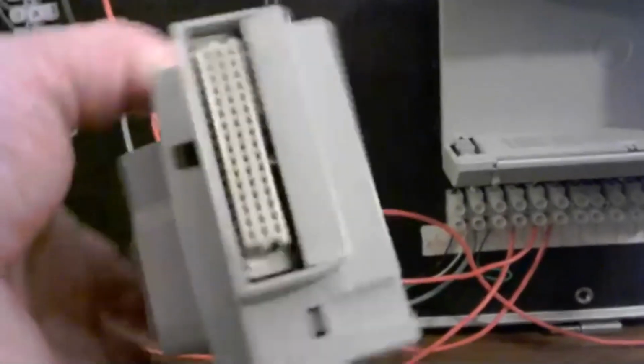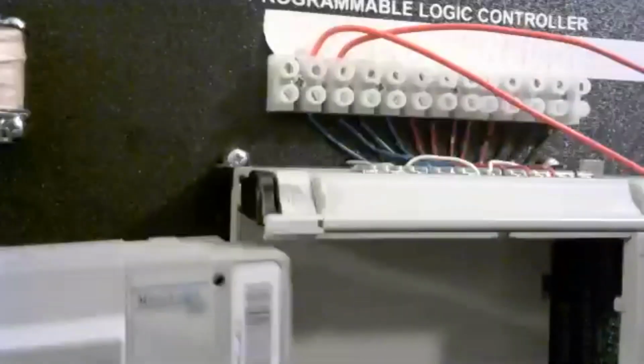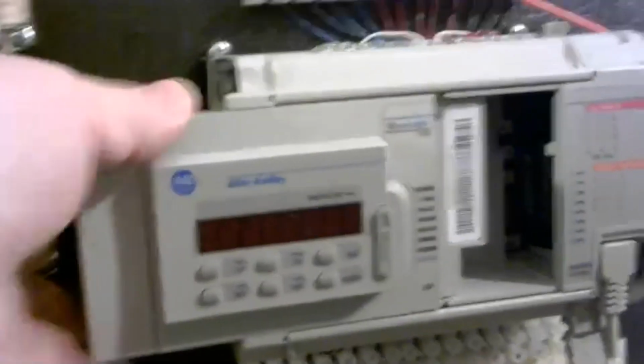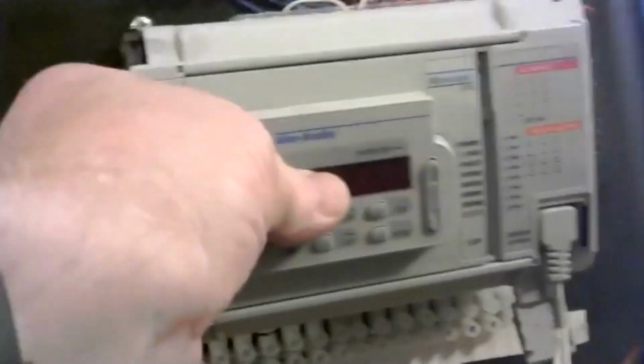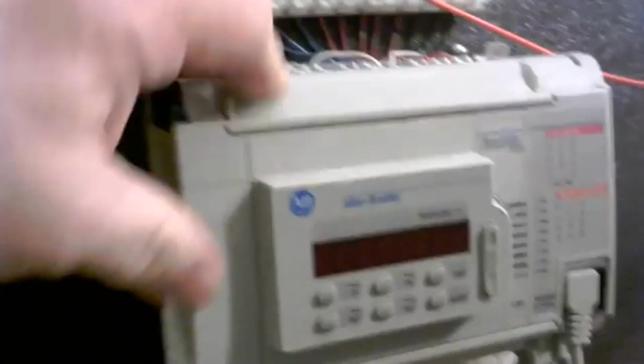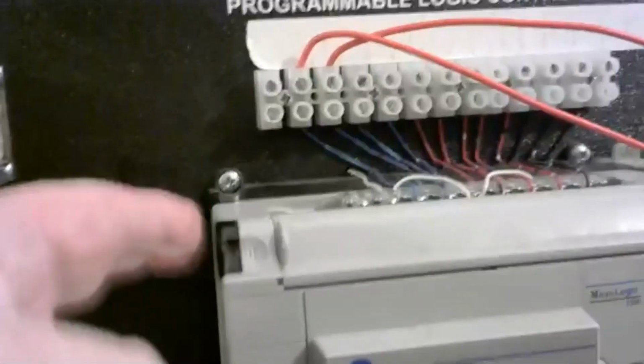You see those little connectors on the side? They go inside into that port internally like that. Can y'all make that out? Yes, sir. Now you have to very carefully slide that thing back into a tongue and groove set there, and it goes back in really easy. Then you want to push and hear it click. When you get that snap, that little release actually locks itself back, and then you're good to go. Make sure there's no cracks in there, that it's all fully engaged, and that you heard a good click.